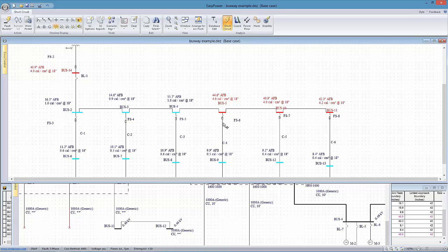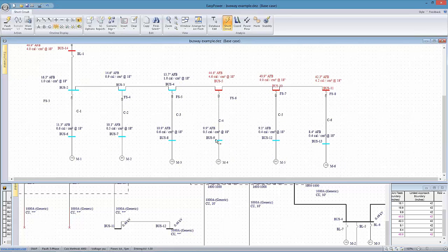But let's say I move this particular load or this particular group of loads from, in this case, I've got them lumped at 200 feet. So let's say I move one at 75 feet and the other one has to go down to 130 feet. Now I'm breaking this up. It doesn't change the way this is all handled. And again, the differences are going to be up here in the busway itself. The drops and the ability to control that energy is still primarily between the connection point or the bus plug and things downstream.